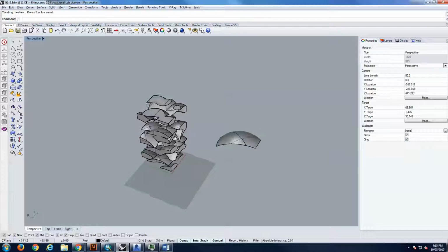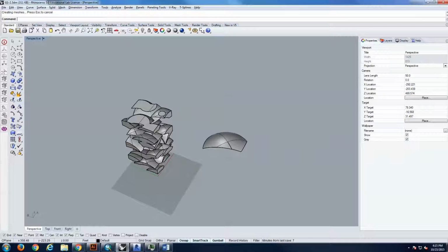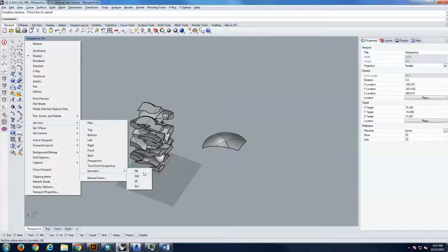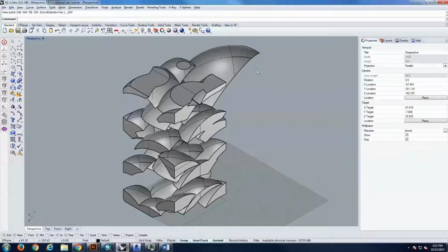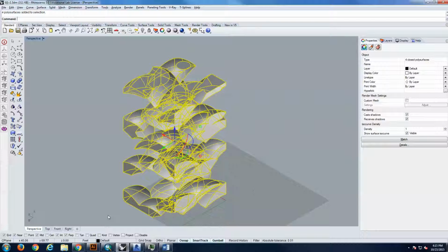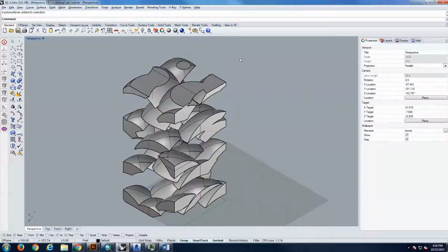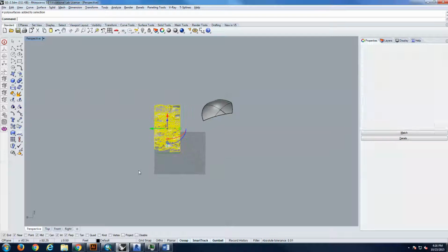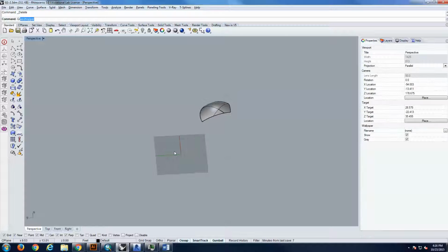Now again, I don't have to say this because you have done it thousands of times, but you go to your specific view. I don't know if you're using an isometric view or any other view, and let's hide this one, and you make 2D and you create a new proposal. You do the extract lines with the make 2D, you take it to Illustrator, you fix the line weight and quality the same way as the rest of the drawings. You make a PDF or you drag it into InDesign directly. Okay, I'm going to delete this proposal because I'm going to talk a little bit more on Grasshopper.